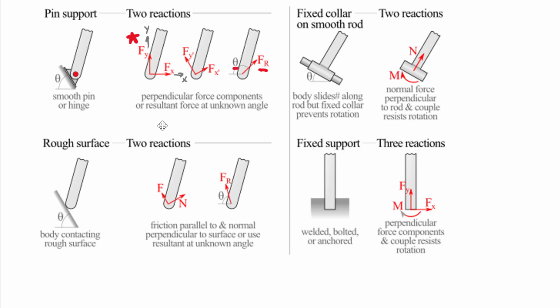To be honest, that isn't the most efficient way to solve a lot of these problems. For one, you get some nonlinearities from always having the sine or cosine of an unknown angle inside as you're solving. And then additionally, you end up with two unknowns in each of your sum force x equals 0, sum force y equals 0 equations. And so it just makes it a little bit more cumbersome, hence why we like to isolate the unknown components in the direction of those axes. And of course, if you rotate your axes, I'd rotate the components. So that's what this middle one is showing, just picking other components if you've picked a different axis.